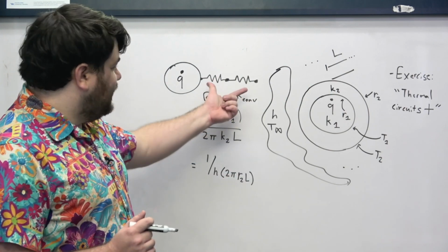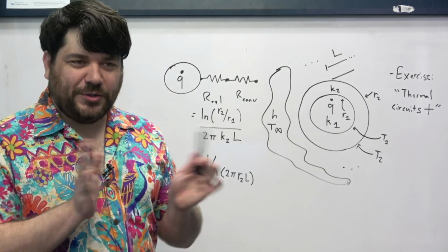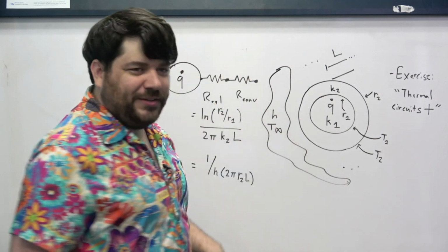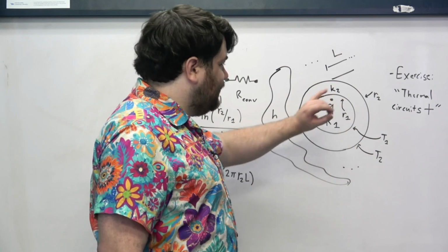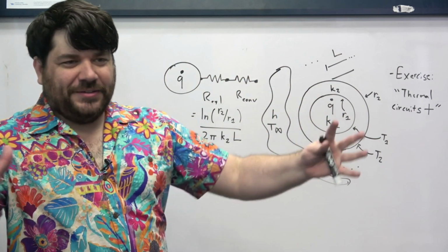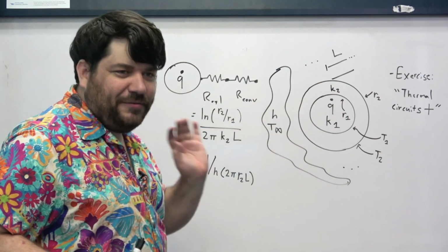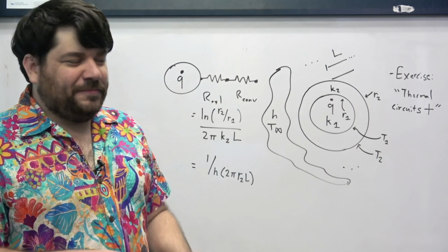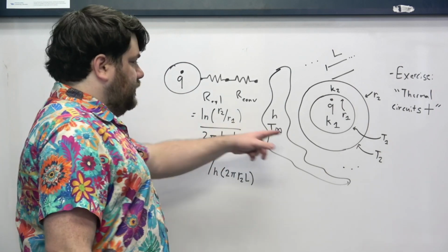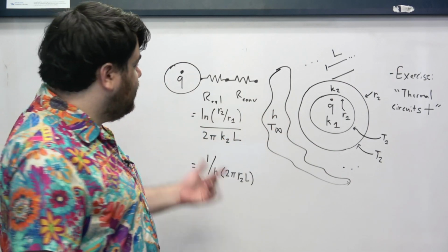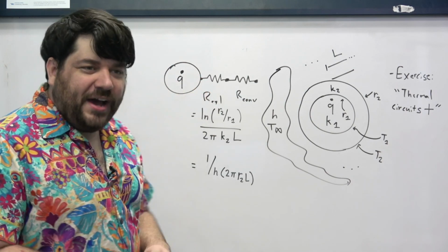And so this is a pretty simple series thermal circuit. It's connected in series, right? Because remember that the direction that we care about is outwards. And so you can see that if we think of outwards as a single direction, the cladding and the air come in sequentially, right? The cladding isn't split in half, with half at the same radius having different material properties, or something like that, right? This is just a nice series circuit. So the only thing that's really new and tricky about what we're doing here is this Q dot, this little ball.